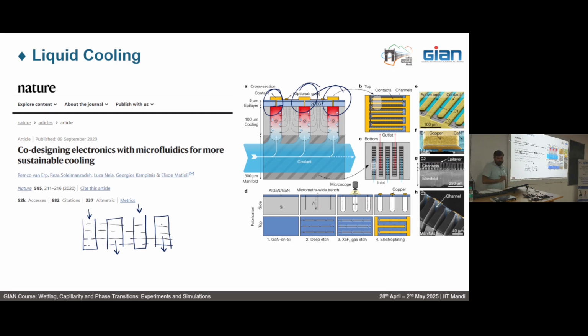So if we see the front side of these channels, the flow is like this. We have a manifold here, the liquid enters from this side, it goes under, we have the buried channels, it passes through it, then it comes out from the outlet manifold. That is the flow configuration in these manifold microchannels.